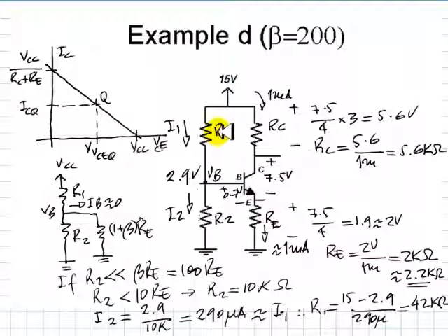And that is the resistance here. Of course, now we have the task of finding commercial values for all of those resistors and recomputing that. And we should rest assured that this circuit is going to keep the transistor not only in its linear mode, but also it will guarantee some room between the cutoff mode and the saturation mode for the signal to swing as widely as possible.